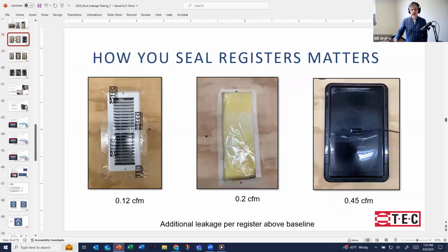Yeah, and I've gotten this question a few times too. We actually have, I'll make a note, Jake, a write-up of why you need to still seal these registers during a duct leakage to outside test. And part of it is also that you now get two big numbers you're subtracting to try and get a small number estimation.